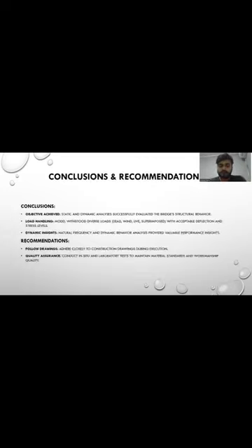For the design verification, we used a simply supported model, which was actually a simpler version of the whole project. We applied a 1.85 kilopascal load, and similarly a linear static analysis with a 5 Newton per meter load. We noted that the structural model and simply supported beam deflection results were not too different, which validates our results.